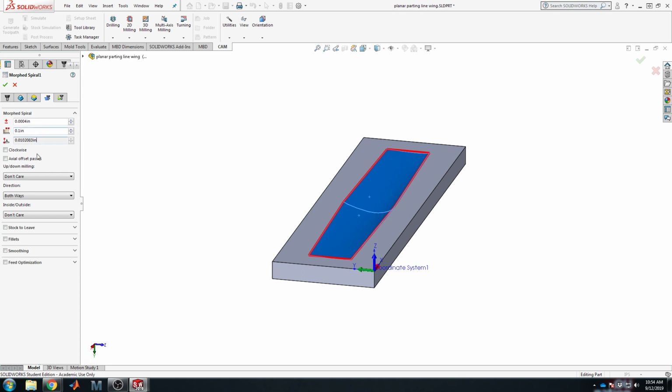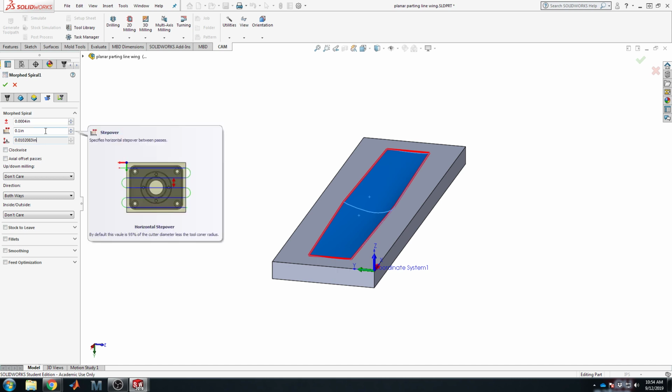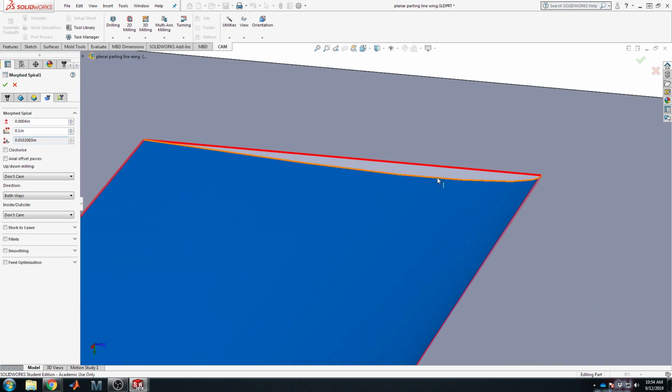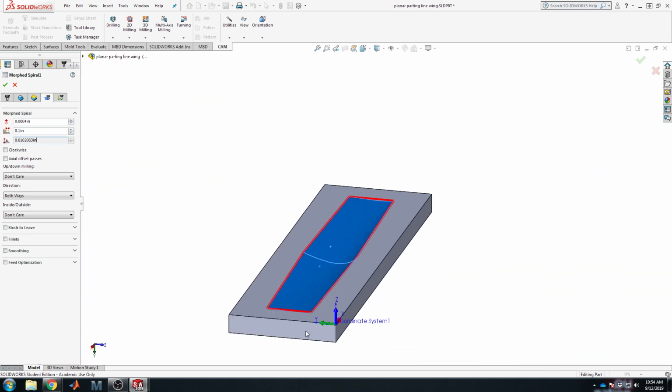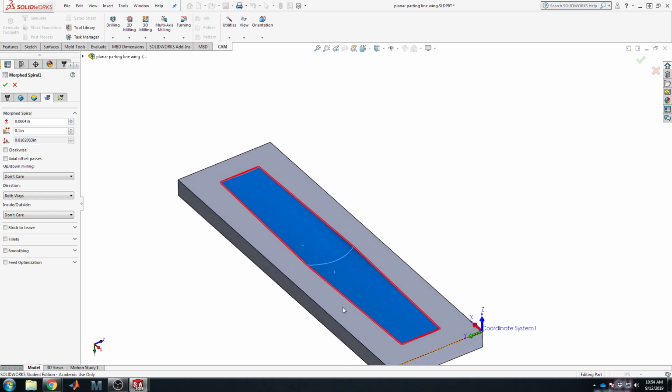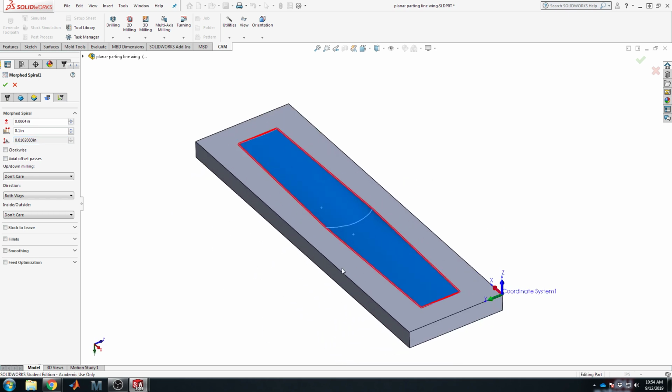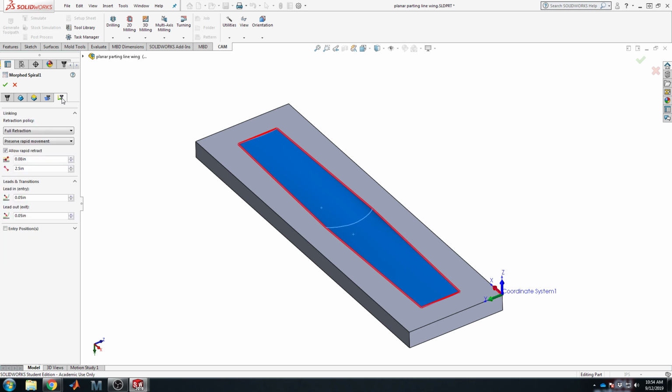So let's go 1/10th of an inch for now with a 1/2 inch ball mill bit. By the way, there are advantages in having a larger radius and reducing cusp height, but obviously if you have a larger radius on the end of your ball mill bit, you won't be able to get as tightly down in these edges and corners, and you need to really watch what the maximum curvature, I should say the minimum curvature in your part is, to see if you can even cut that.